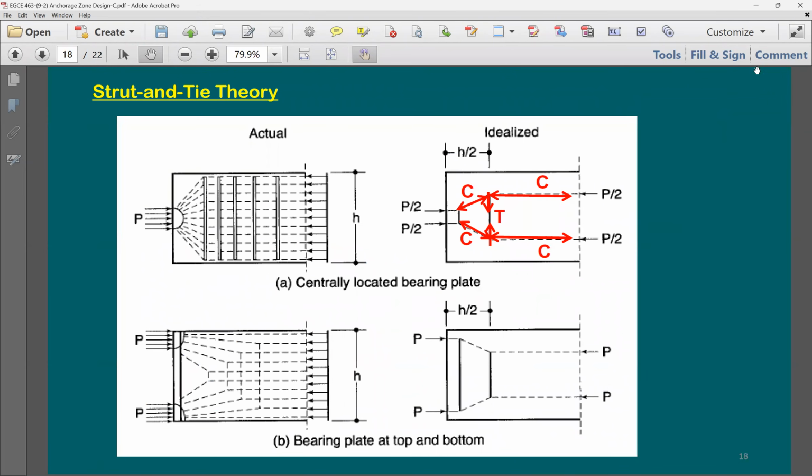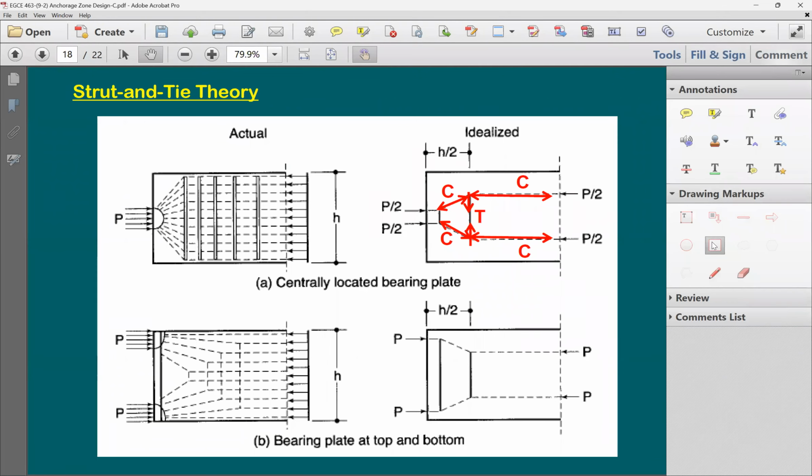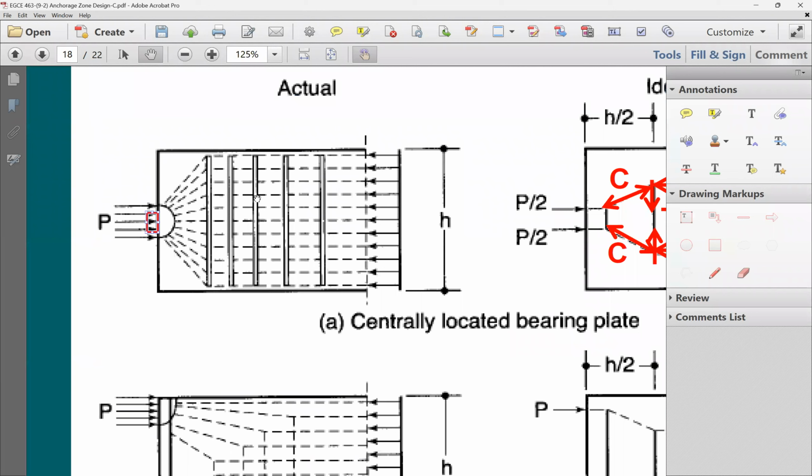Here's the anchor plate length. It has a length. This is why you just take 1/2 of P and put it on the top, put it on the bottom, so your angle is going to be slightly different. When you put a bigger plate, what's going to happen? Let me start here by putting a plate. Let's say the plate at the end is very small. Therefore, the location of both of these two forces is going to be close to each other. If I assume that this plate has a zero height, almost the height is like half an inch or nothing, there's going to be a 0 point. There's going to be 1 point load. This is going to be P.